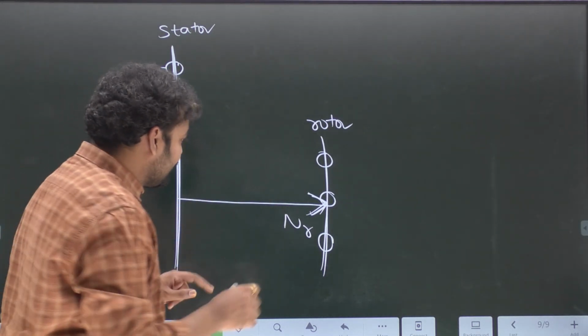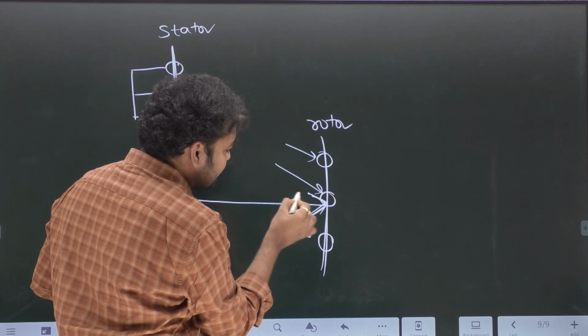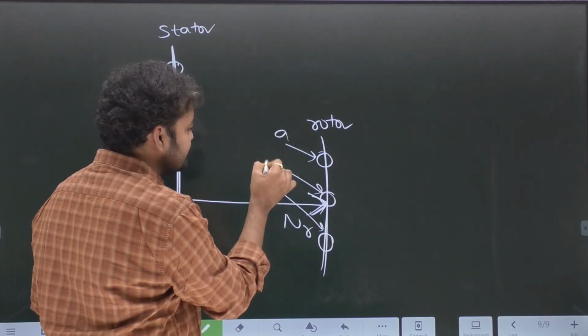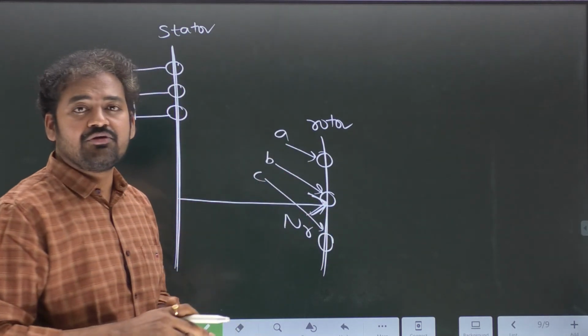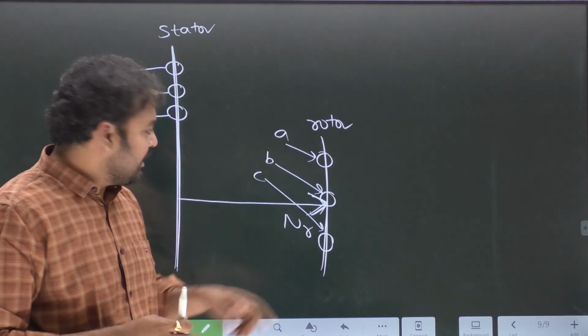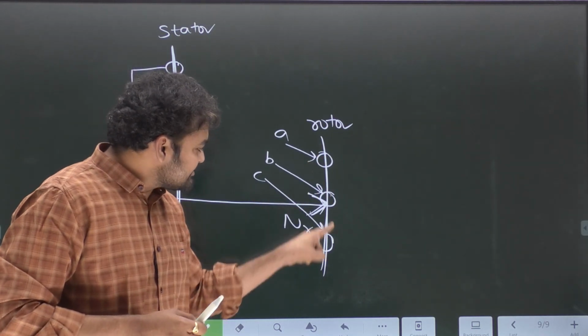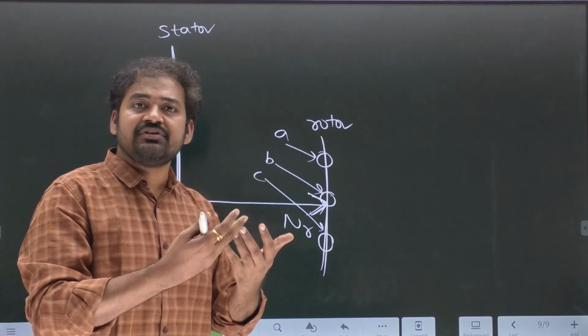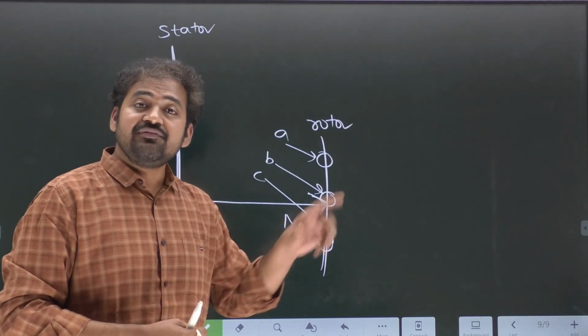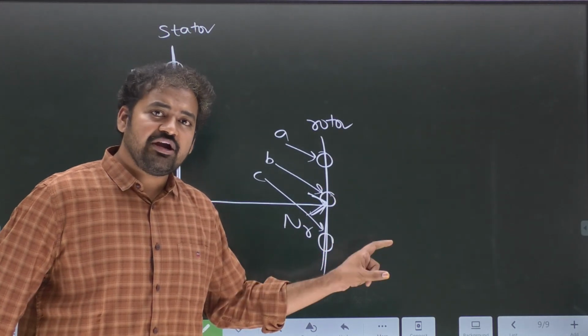Now this rotor winding is excited using an ABC sequence supply. When nothing was given, we have to assume positive sequence. And whenever a three-phase balanced winding is excited with a balanced supply, it will create a rotating magnetic field.